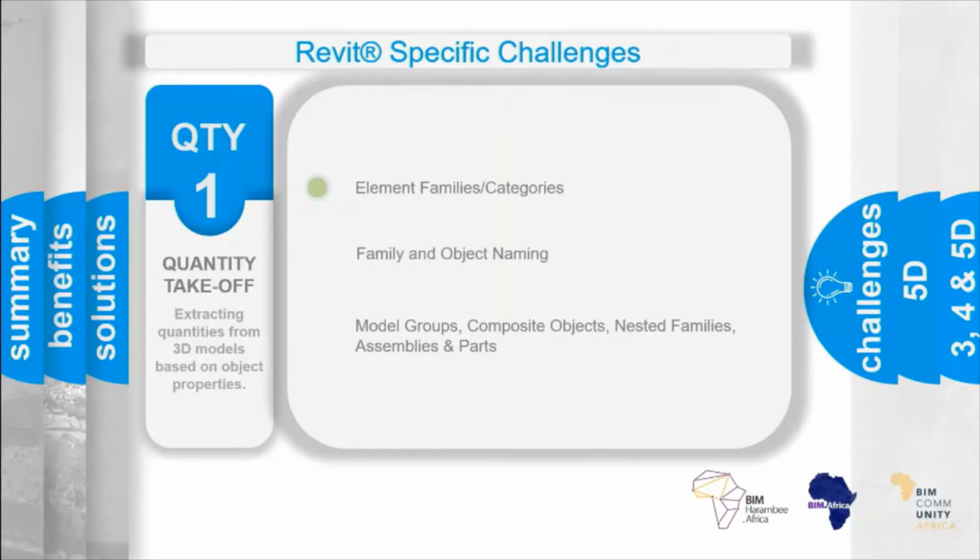But in instances where modeling best practice doesn't align with the direct category, for example, bulkheads being modeled in walls using the walls family, it's very important that the type name of the model object clearly indicates the intended finish of that element and must be noted as such in the BEP.